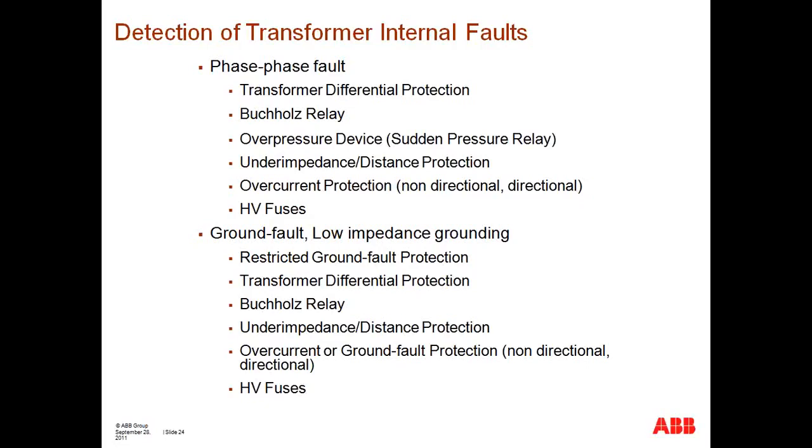It provides, to a certain extent, good sensitivity, since when any type of electrical fault occurs, there's going to be this breakdown of oil. So this is not an electrical or a microprocessor device. This is a mechanical device that's built in as part of the construction of the transformer.